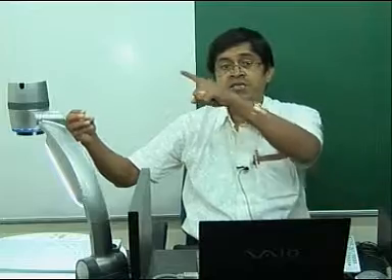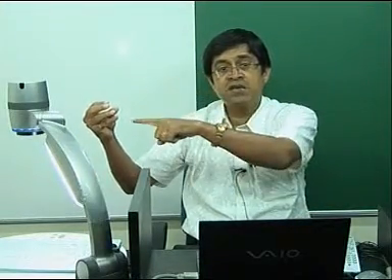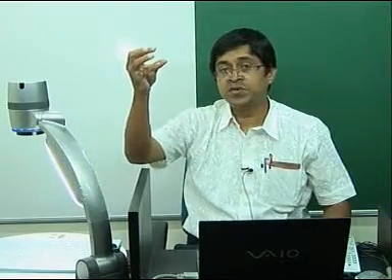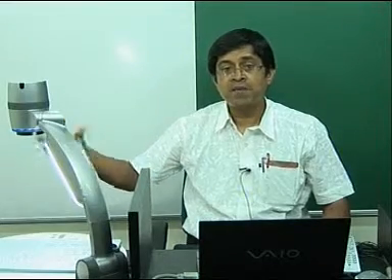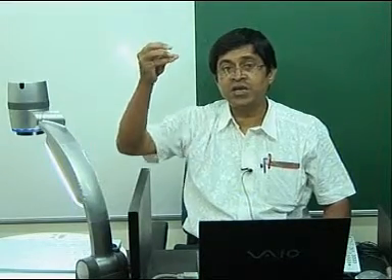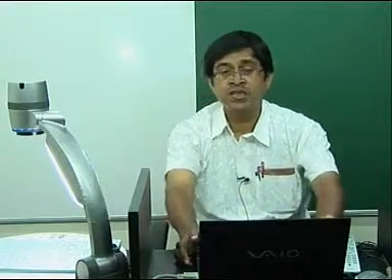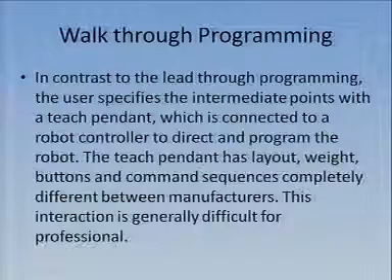These 2 points here and here I do not teach anything, those calculations I will do using a program. So, lead through is where every point I teach, but walk through is where I teach here and the rest I calculate. So, it is a combination of lead through and some computation.